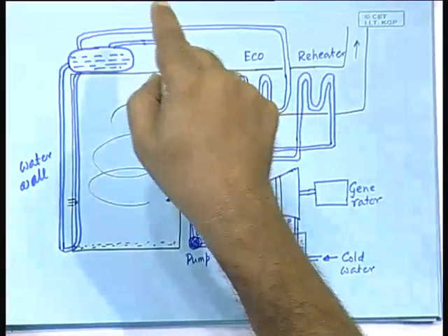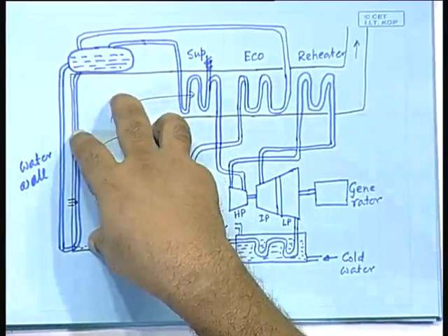That means it is sprayed in very small droplets into the chamber, that is ignited, temperature builds up, and only then can coal particles catch fire. So, whenever there is a startup, you need input of oil. After the startup, the oil injection is no longer necessary, it is the coal that can sustain the fire. So, that stops. But every time you start up, you need a lot of oil. And normally the relatively heavier ends of the petroleum products are used here.